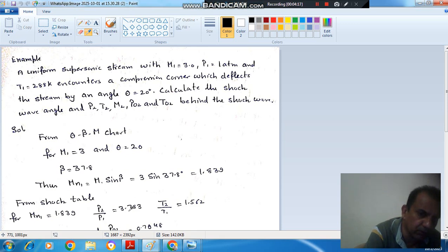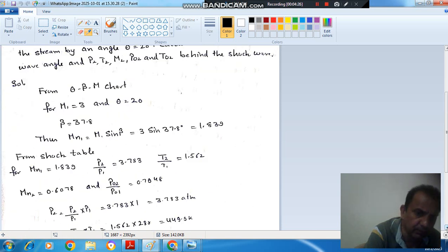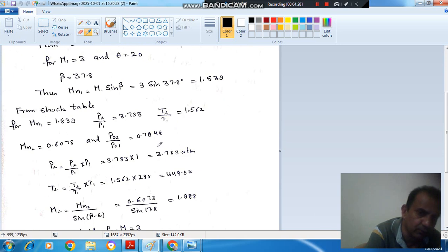So that P2 by P1 is your 3.783, and T2 by T1 is 1.562, and P02 by P1 is your 0.7948, and M2 after shock is 0.607.